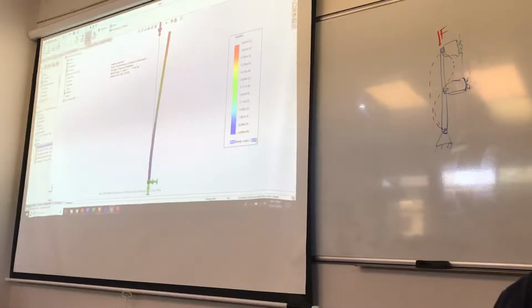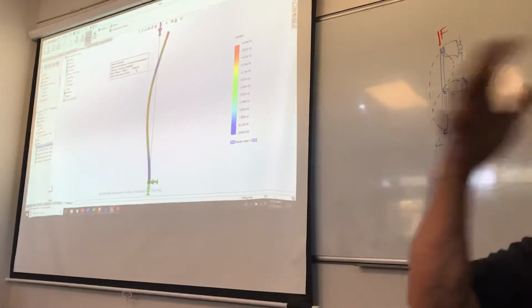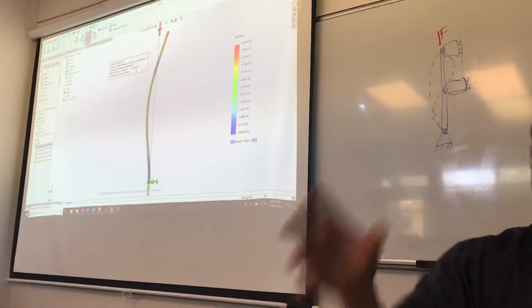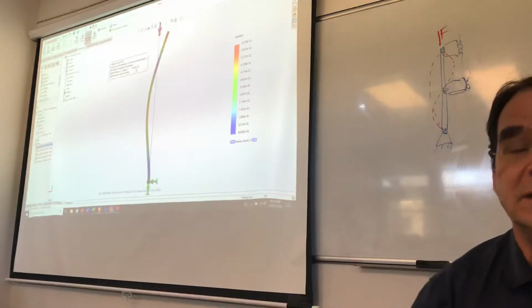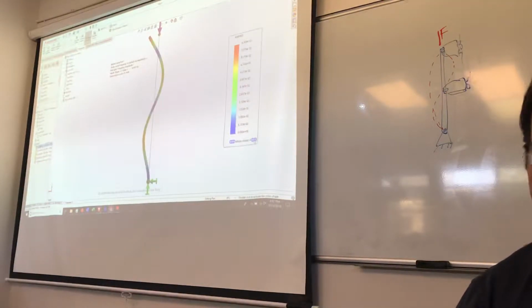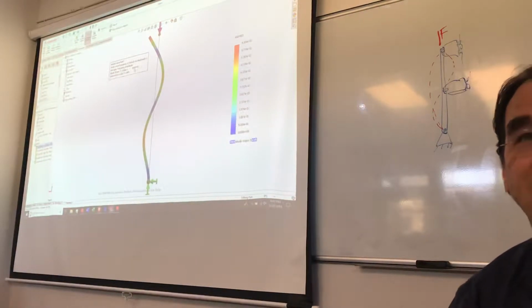And then we can look at the higher modes, which are now up at 10 hertz. There's an 11 hertz mode where it's oscillating back and forth. So that means it's going back and forth 11 times in 1 second? Yep. Now, it's not oscillating very much. The higher frequency ones typically have much smaller amplitude, as a rule, but that's another harmonic mode in there. There's basically an infinite number of them. And there's the fifth mode, which is up at 30 hertz.